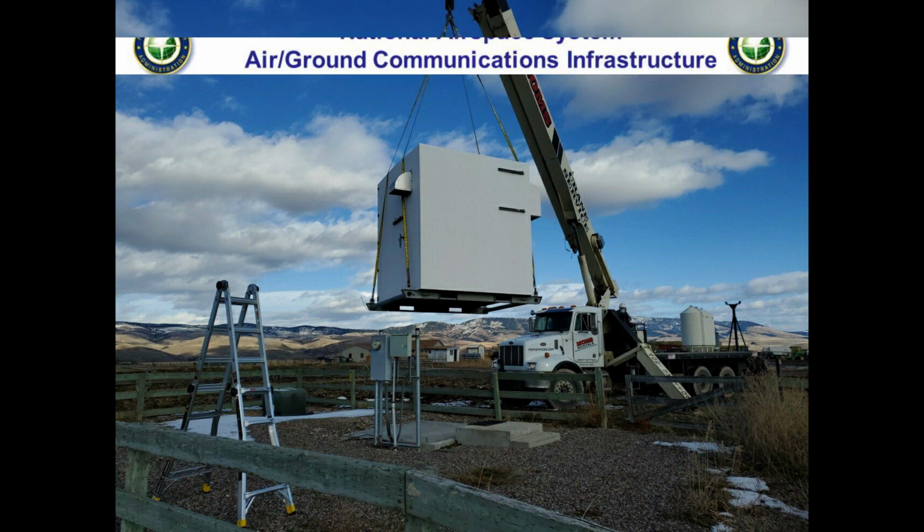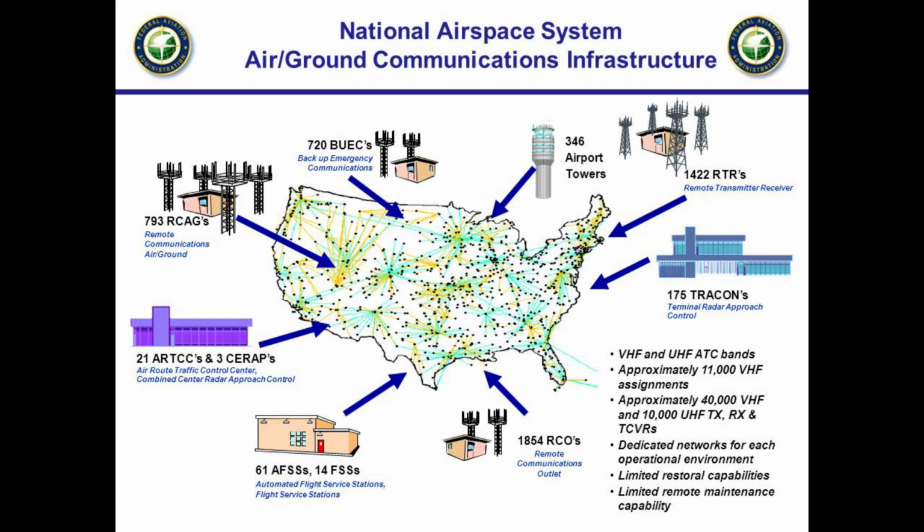Ground Communication Outlet. Ground Communication Outlets, GCO, have been developed in conjunction with the FAA to provide pilots flying in and out of non-towered airports with the capability to contact ATC and AFSS via very high-frequency (VHF) radio to a telephone connection. This lets pilots obtain an instrument clearance or close a VFR/IFR flight plan.